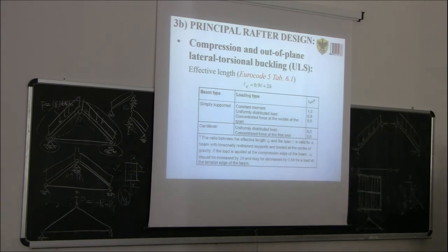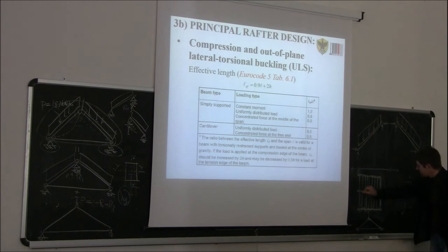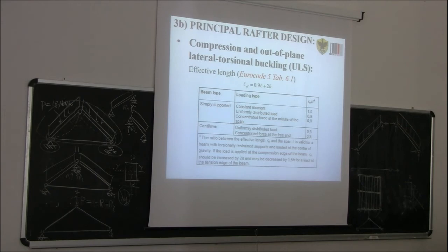So even if those purlins are fully rigid, are they able to prevent a buckling like this of everything? No, they are not able. They just transfer this lateral deflection to all the other trusses, so all the trusses buckle simultaneously. So the purlins alone are not enough to prevent this possible lateral torsional buckling, not only of the rafter but of the other frames in this case. Okay?